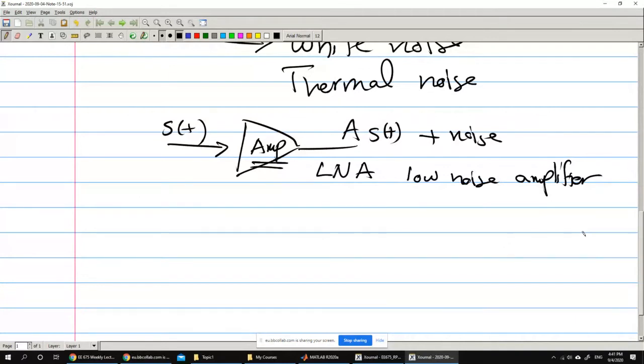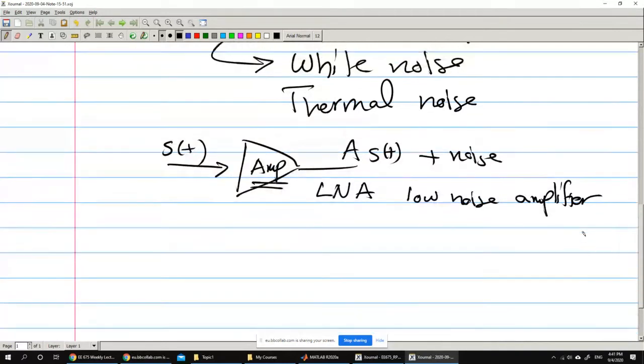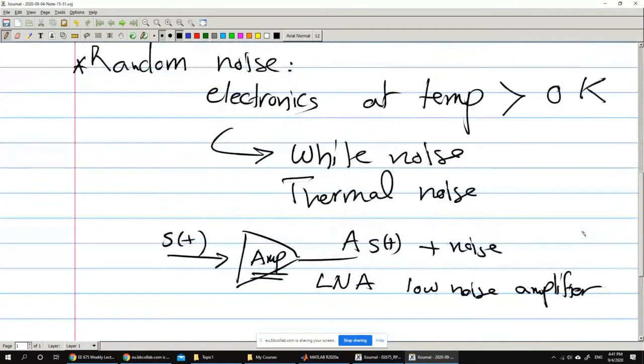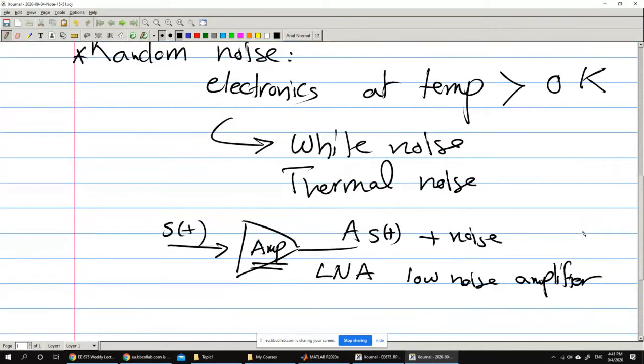Are we dealing with random noise in ECG? Definitely we do, but for random noise you usually have very basic amplifiers and very basic filters, like we're going to talk about in a second. We can have them as analog signals in the acquisition, and in designing the amplifiers we use the lowest noise amplifier that we can get.